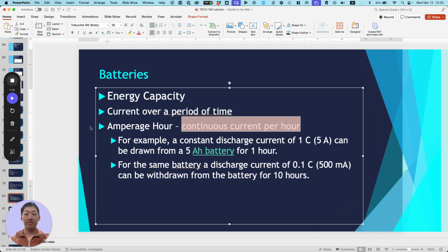It might make a little bit more sense here. Okay, so this is a 3-cell battery. We're going to look at the first cell, positive, and then the last cell, negative. And you see they're connected in series, so we get the total voltage, because in series you add up the voltages. Now let's look at our balance lead right here.